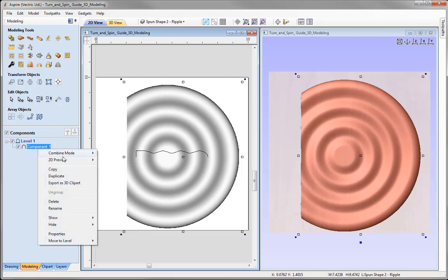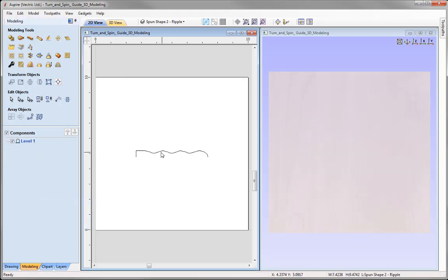So let's just right click on that component. I'm going to use the option here to delete it. Now let's have a look at actually positioning this vector so that we can fit the entire circle in our job space. So I'm just going to select it again to put it into transform mode. I'm just going to pick it up by holding down and snapping to the end point there. I'm going to try and snap to the center of my job vertically and horizontally. So you can see I've picked up the vertical and horizontal lines for my job, and I can click in place there so I know it's in the center there. And so I know that this should essentially fit within the bounds of my job space.